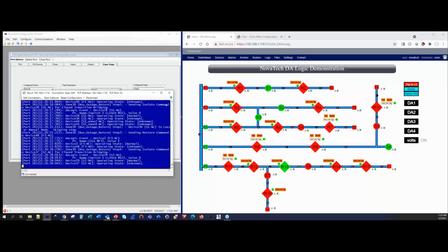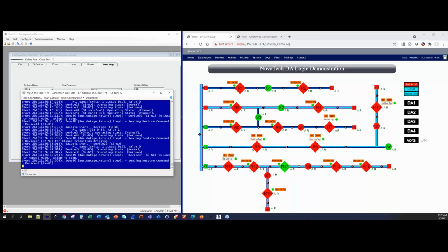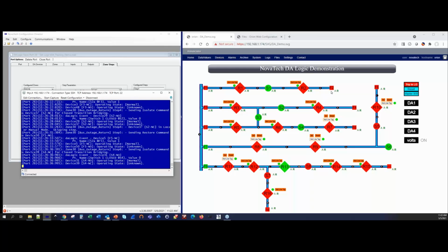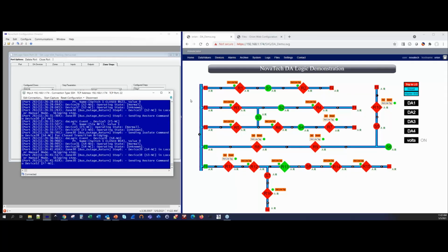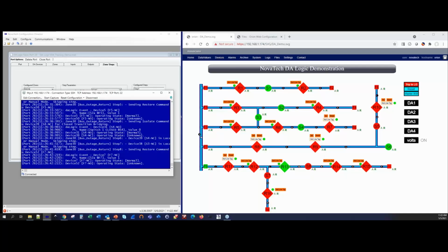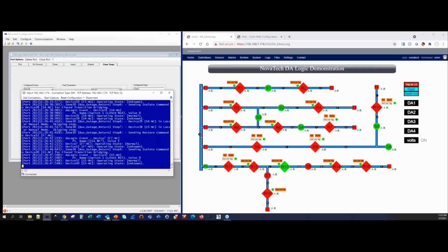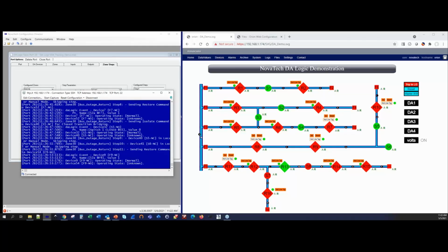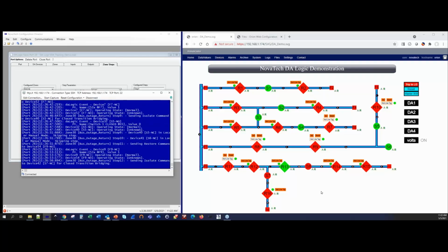And you need to be extra careful in sequencing your restoration. If this was 3 different remote substations through here, you don't just go ahead and close everything and get circulating currents between multiple substations that would be occurring during the restoration. You have to make sure that you sequence your steps to be one at a time and controlled.